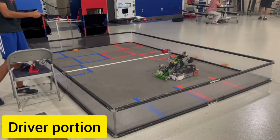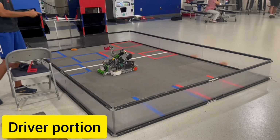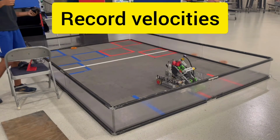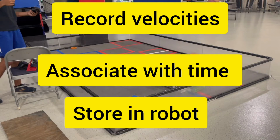Traditionally, robots execute pre-planned code. However, in an effort to redefine autonomous programming, our team found a way to convert driver movements into code that could be run on the robot. The solution that we came up with records the various velocities of all the motors and positions of the servos and associates these values with a timestamp. It then stores these lists of values in a file in the robot. We then are able to read and execute this file during an autonomous period.